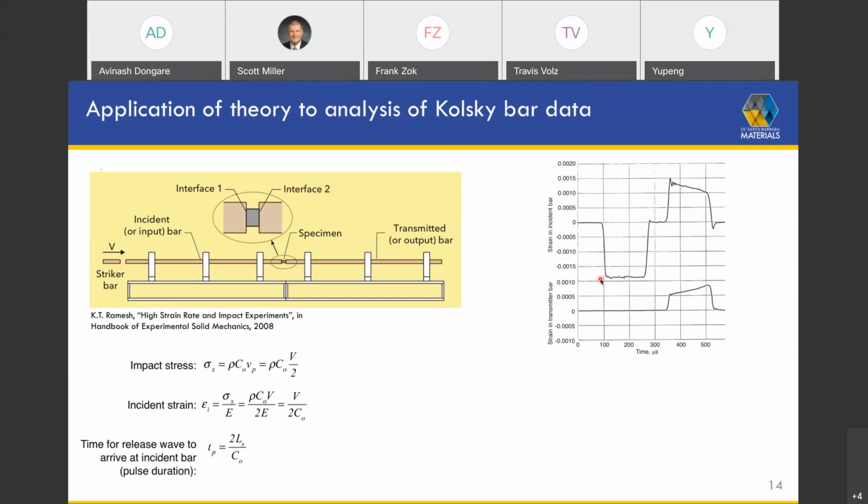Now, as you go up to even higher strain rates, what you find is that the displacement rates, the speeds of dislocations, are now starting to approach the shear wave speed in the material. The shear wave speed is essentially a limiting maximum speed at which dislocations can move, because that's the fastest that you can transmit information about shear waves in the solid.